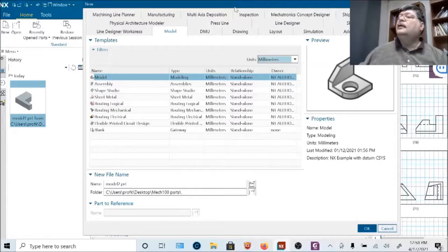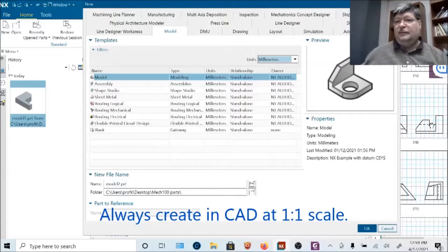The homework over here, when you have the grid, we're calling this centimeter grid paper, so each one block is 10 millimeters. So this overall part is 60 millimeters. This is the right side view, so that'd be deep, 40 millimeters high, and I can't quite see that there. It's 40 millimeters wide, I believe. So make sure whenever you're doing CAD, you always draw to scale. Don't say, well, I'm going to double every dimension. No, always draw it to scale.